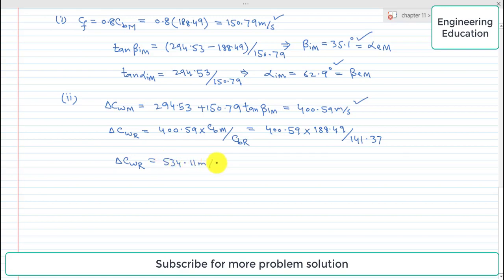Similarly, to find the value of delta CWT, which is the change in whirl velocity at tip, it is equal to 400.59 into 188.49 divided by 235.62. So simplifying this, we get the value 320.46 meter per second.